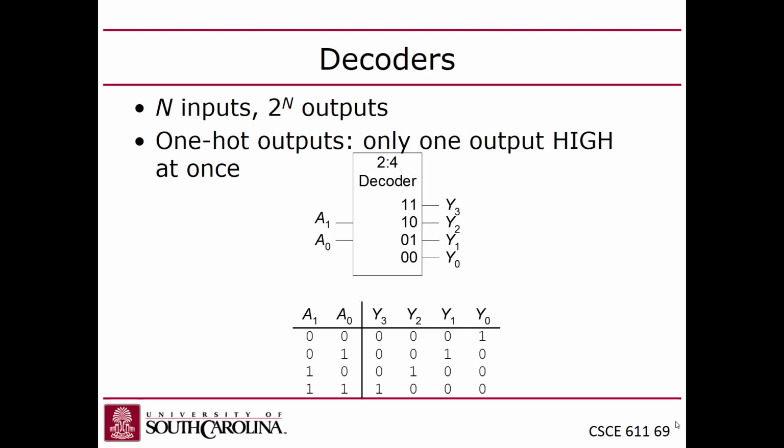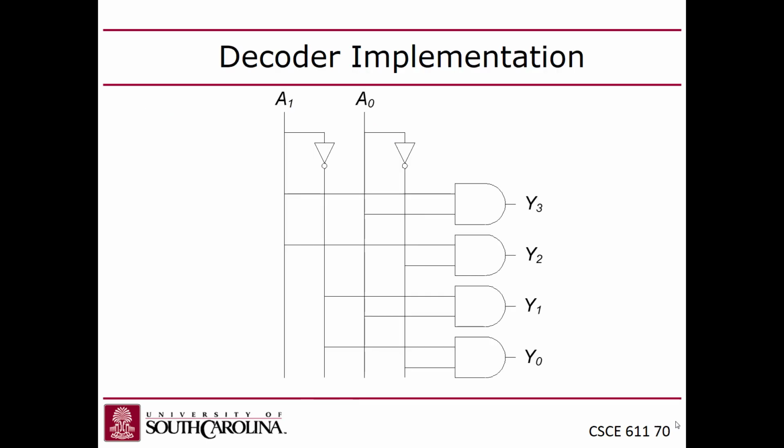So this idea of memory hierarchy is really important, but the question is why? Why is it that bigger memories are slower? It's because of the decoders. The bigger you make the decoder, the more outputs you have, the more stuff that has to happen inside there, and so they're slower. And decoders are fundamentally built with logic gates like everything else.